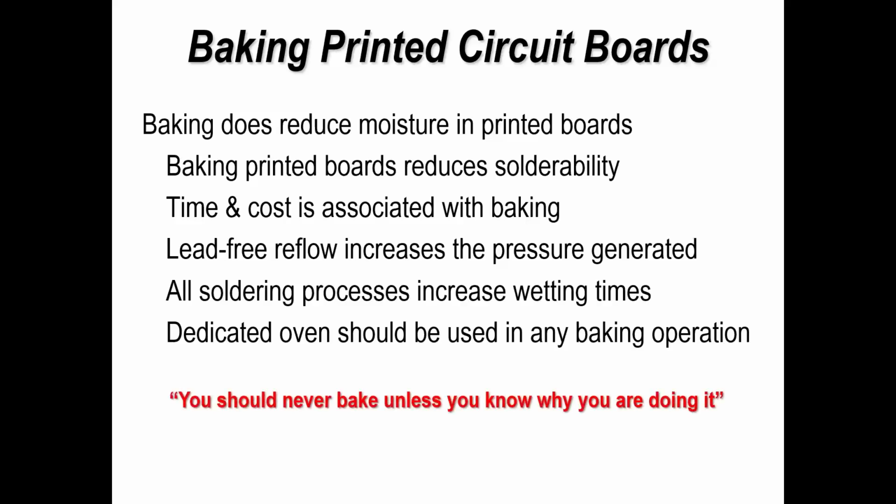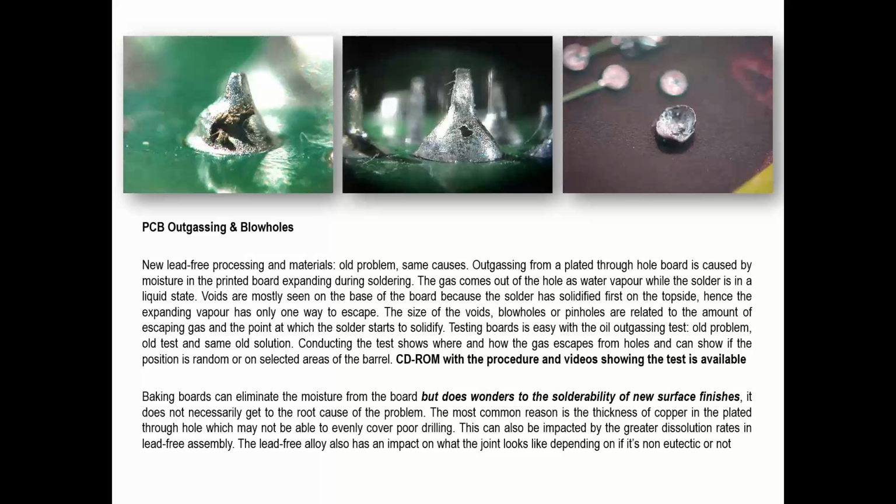Remember what I've said? I'm just emphasizing it again: never bake unless you know why you're doing it in the first place. So let's pick up a couple of common reasons why people bake, other than cracking of parts, which is all to do with our subject of today, which is moisture sensitivity. Blowholes and pinholes. Now, I've been talking about this since my 20s, but it's still a problem we see today. Each one of these examples is in a lead-free process, but they could be in a tin lead process.